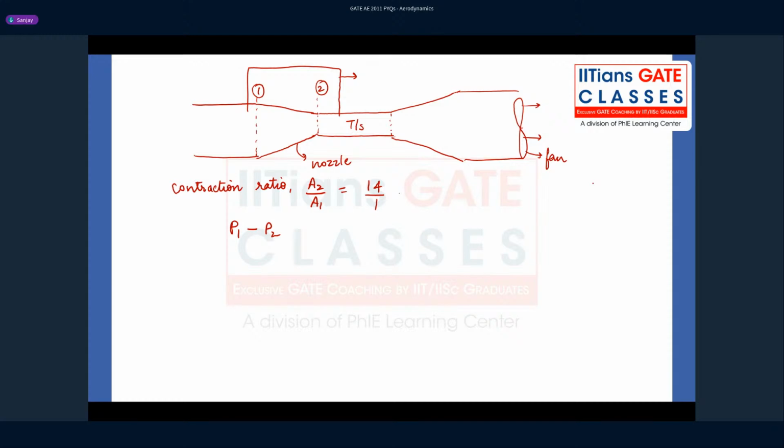Okay, you know it's a nozzle, so pressure is going to decrease, right? Because the flow will accelerate. So P1 minus P2 is 40 centimeter of water column. Okay, now how will you interpret this, guys? If it is 40 centimeter of water column, you know the difference in hydrostatic pressure is nothing but rho g h. Okay, so it is water, it is going to be rho water times g into h.